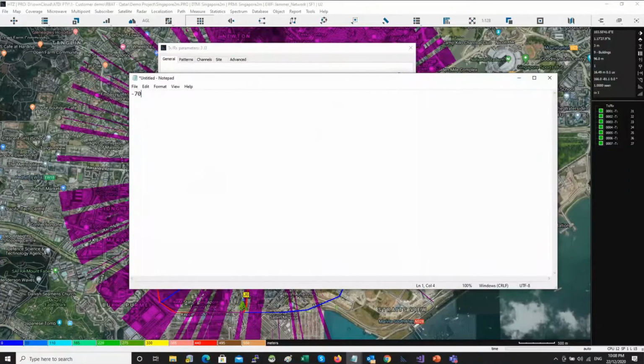So you can predict the coverage of the jammer. And let's say negative 70 dBm is a strong signal. That's what you would, for example, expect as the wanted signal. If J over S needs to be equal to 20 dB, the jamming signal must be 20 dB greater than the signal. Another way to look at this is to say J is equal to negative 50. That's a simplified way.